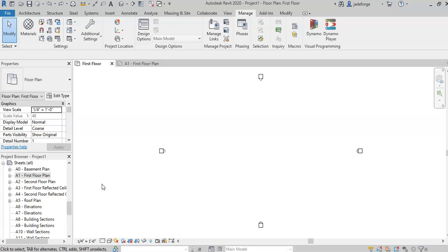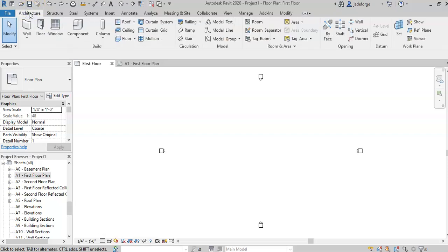It is going to have you use a generic 8-inch wall that they will change on you on page 5-15. So we're going to stay with the 8-inch right now, just for purposes of teaching. In this lecture, I want to make sure I'm showing you how to use the grips on the temporary dimensions and how the extension lines are being pulled from.